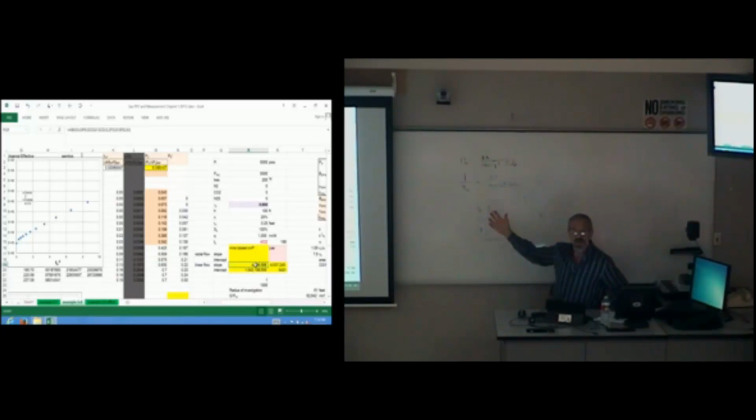So, as we know, we've had an argument earlier about whether we should use T sub P star. A buildup, if you're going to use T sub P, has to be produced at exactly constant rate and then build up, okay? Now, we really hardly ever know that in the oil field. We hardly ever produce a well at constant rate. Exactly.